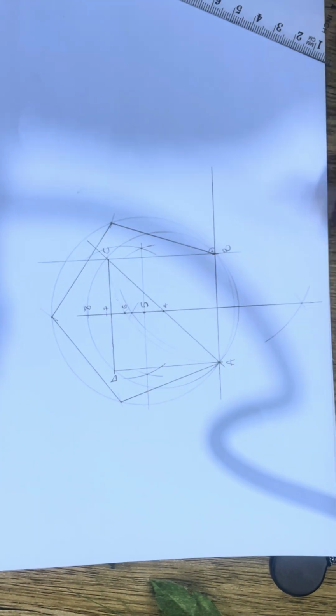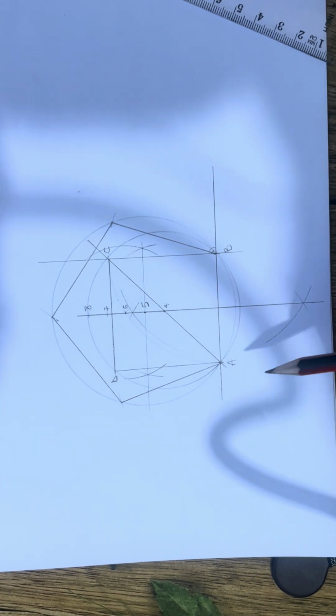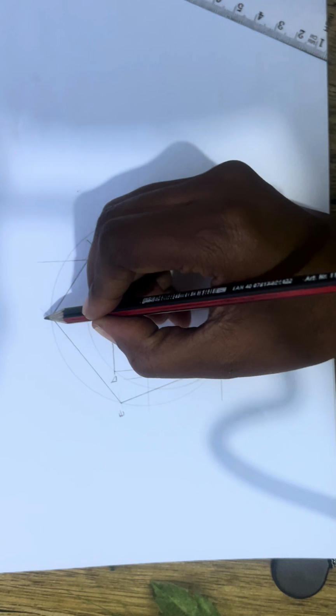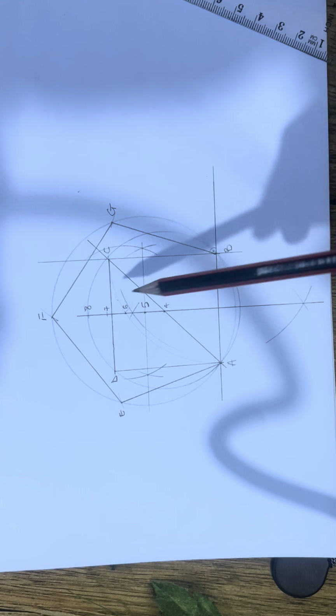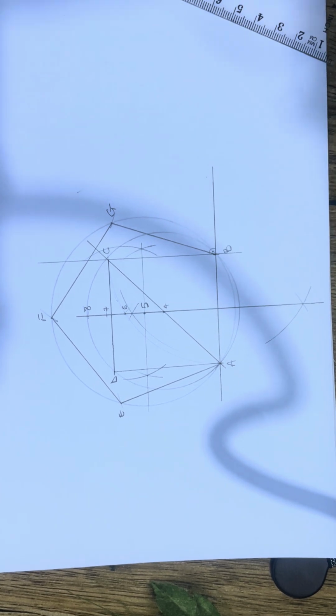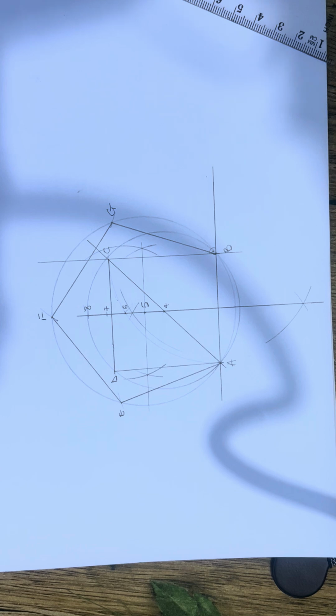So there you go. So we have our pentagon A, E, F, G. If you want your hexagon, you use 6 as your center and you draw the circle. Pick the distance AB and hatch it around the circle, okay, to come up with your polygon. You do that for respective polygons according to the way you want it to be. So that's how you draw. That's a general method of constructing a polygon, any number of sides of polygons.